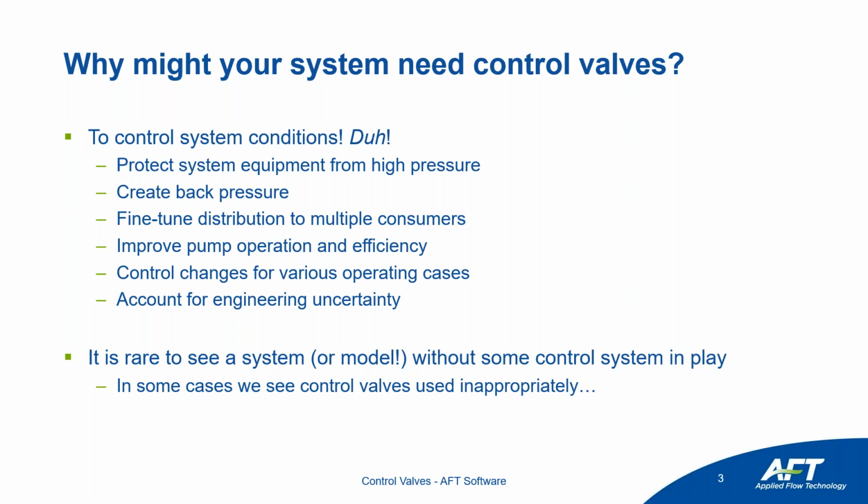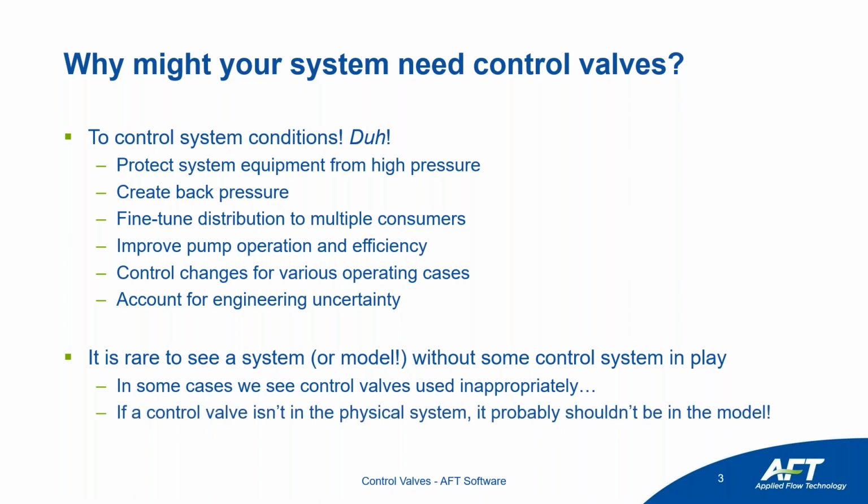So very commonly, if you see a pressure junction with a flow control valve very close to it, or vice versa, that should be concerning in the mind of the engineer. And a general rule of thumb, I would say, is if a control valve is not in the physical system, then it probably should not be represented in your model.